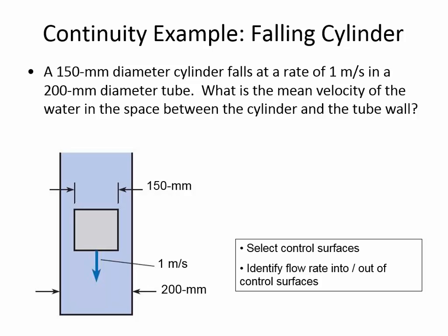But if we change the control surfaces to say, well, we need to cut through this surface because that is where something's happening. That's where the flow is going out. And the same on the other side, we need to cut that surface because that's where the flow is going out. And then we think in 3 dimensions. Well, that's not 2 sides. That's really one continuous ring. Okay? So that gives us the outflow, and then the inflow is just going to be that cylinder.